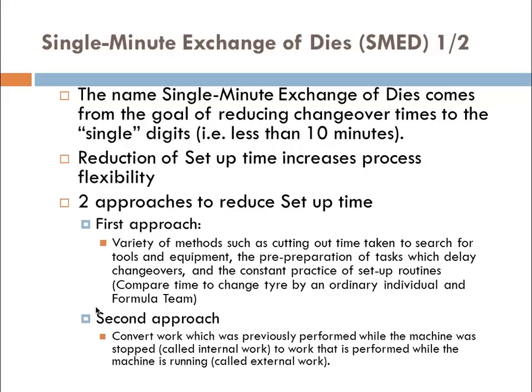In addition, setup reduction can be achieved by a variety of methods, such as cutting out time taken to search for tools and equipment, or the preparation of tasks which delay changeovers, and the constant practice of setup routines. This forms the first approach.